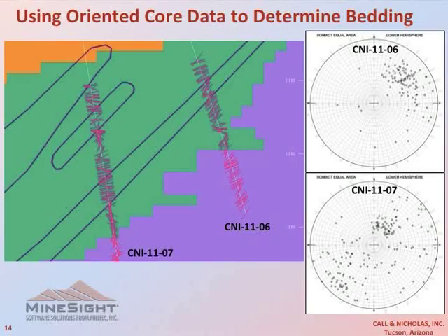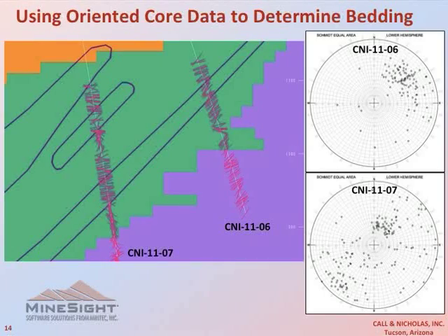We've been using the Geotech tab in the drill hole views, and what it'll do is give us an idea of what, let's say, bedding orientations are really telling us. In this case, we had a modeled sediment in here, and we're able to take what we see as the bedding orientation in the drill holes and help the modeler, in this case the client himself, determine where these low strength shale beds were within that sediment package.